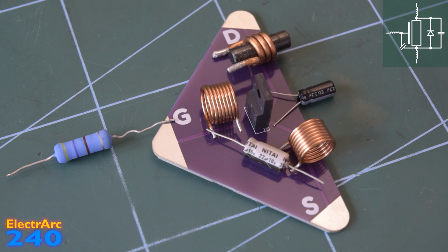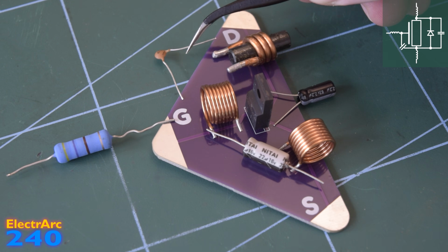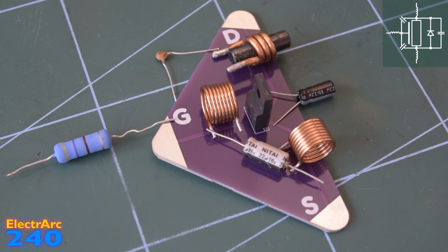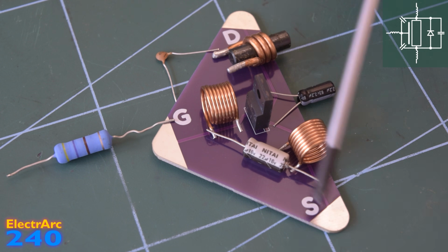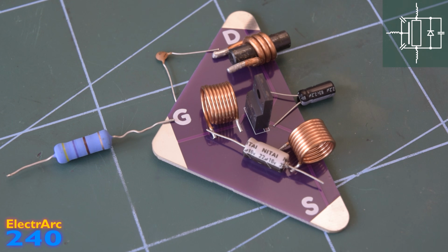We're almost there, ladies and gentlemen. The final parasitic is the gate-drain capacitance, also known as the reverse transfer capacitance. Despite being the smallest capacitance, this is the deadliest in fast switching applications. And that's because capacitors like to try and keep the voltage across themselves constant, and the gate-drain capacitance is no different. When the MOSFET turns off, the drain voltage will rapidly rise. In our example from earlier of the electric car, this drain voltage is going to rise up by 400 volts relative to the source. And generally, the gate and the source, they stay together. The drain is the pin that likes to wander off to lands of high potential.